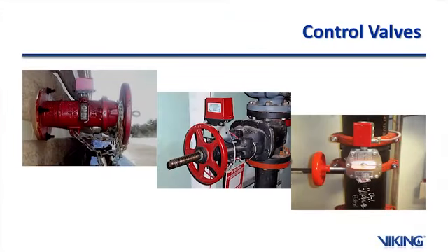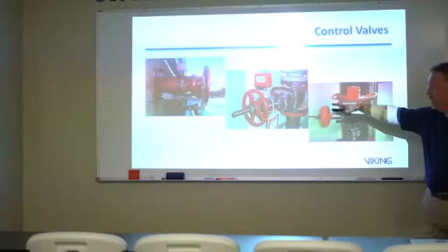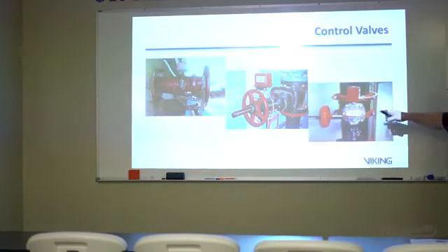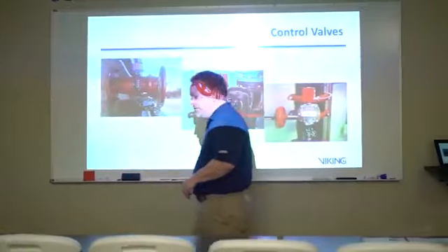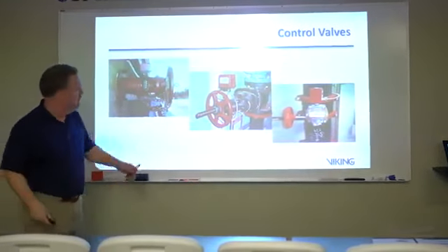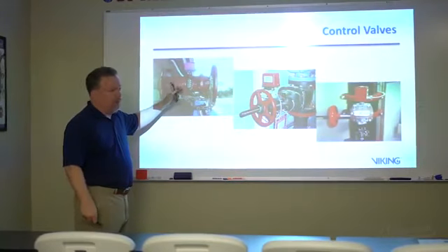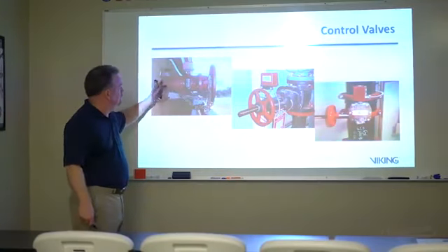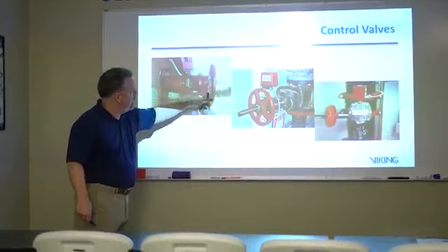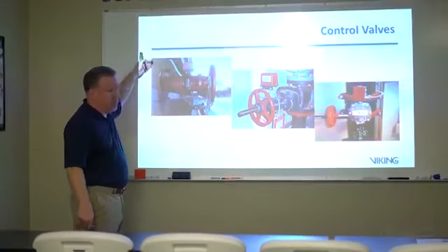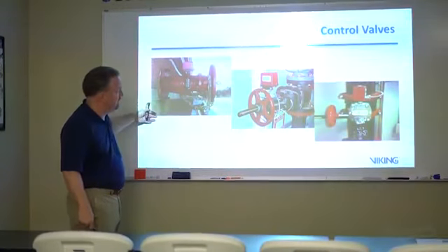Control valves operate simply by controlling the water. So they indicate that they are either open or shut, and there are a couple of different ways that they're done. They have to be listed for controlling water into the building. So open, chained open, sealed. This just means that water's flowing into that system.